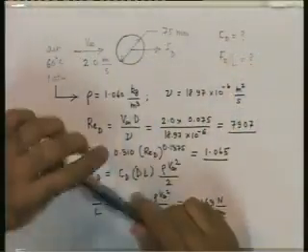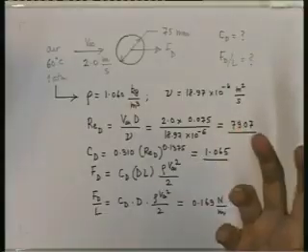This particular illustration shows how to calculate the drag coefficient. In particular, remember that for cylinders, and you will have correlations for a square body or a sphere. These correlations are available in textbooks and in literature. Whenever we have a body except a thin plate which has a significant projected area to the flow, it is the projected area which is used for determining the drag force. It is only for a thin flat plate that we use the actual area of the plate.